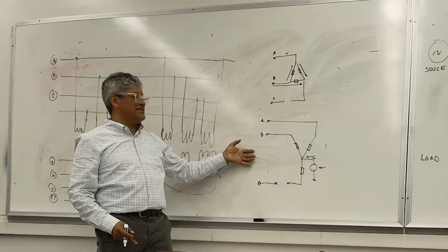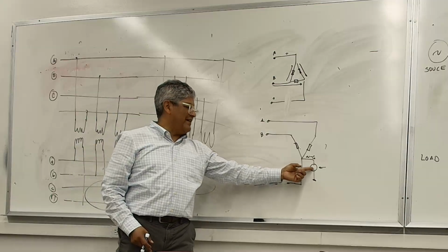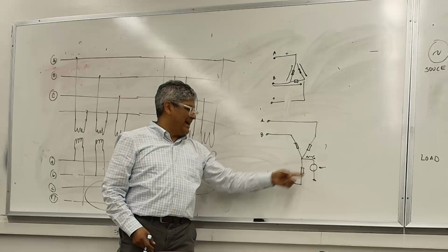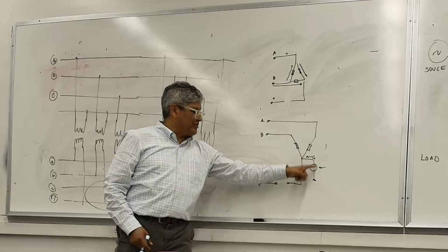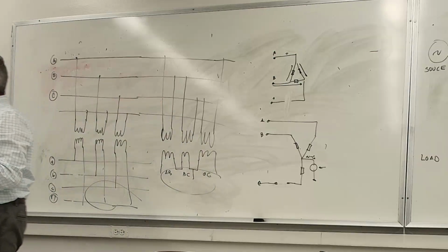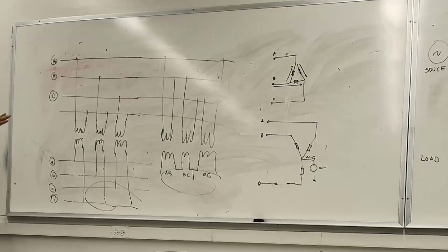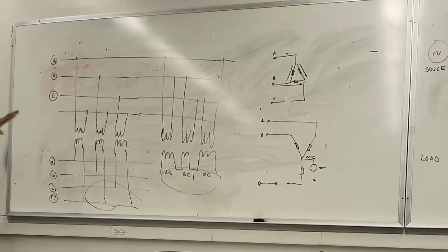But the biggest advantage, as I said, is that you have this connection, and when you have this open, the imbalanced current will flow through that, and that is good for protection engineers. So it depends on the type of the loads that you're going to be feeding.